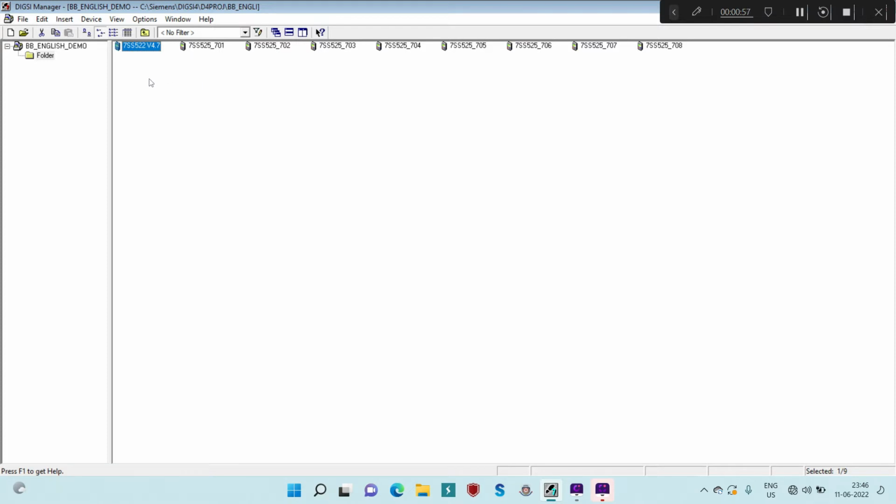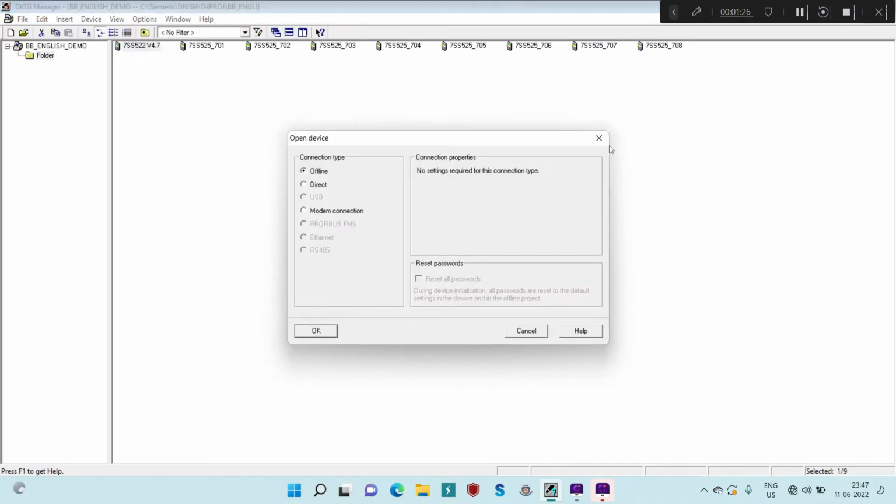If you remember, in the first session we already discussed the busbar topologies, that is, how to create a busbar topology for a 1.5 breaker scheme. And during that session we considered 8 bay units, 4 of which are connected to bus 1 and the remaining 4 are connected to bus 2, and we drew the topology in the same way.